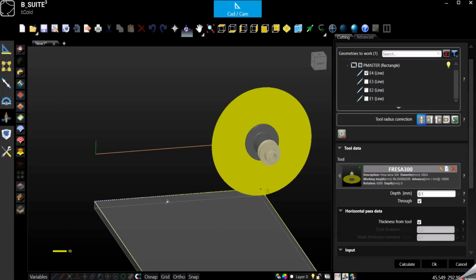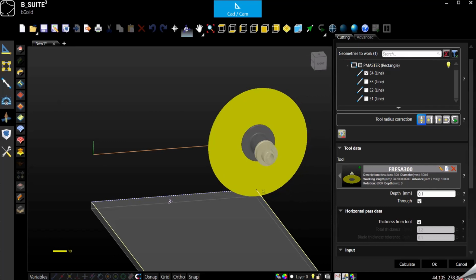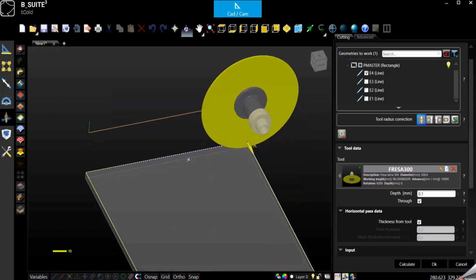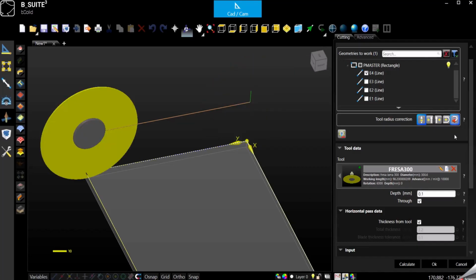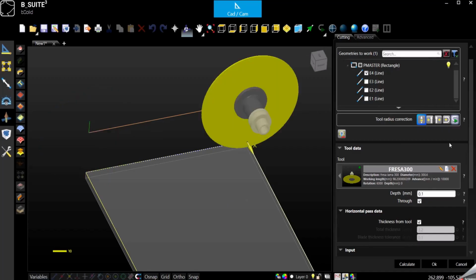Because especially in case of melamine, if you go conventional, it will probably chip the melamine. So the reverse travel eventually will change the starting point of the blade, and as you can see, in case of a 5-axis, the spindle will be above the panel, right?